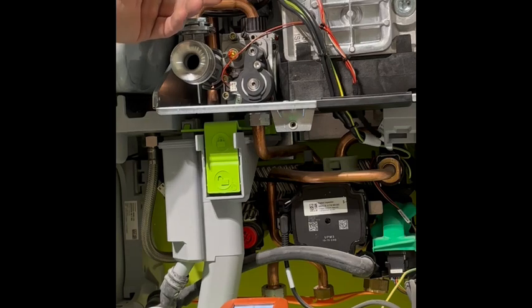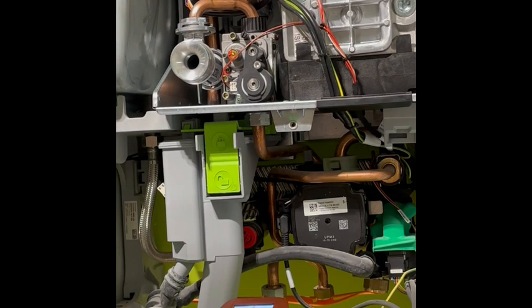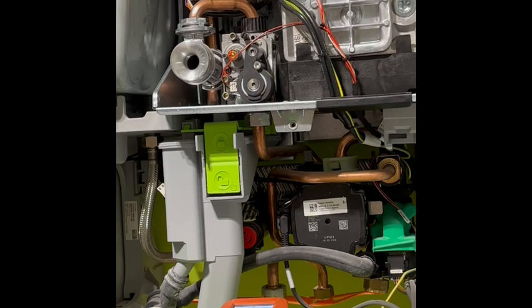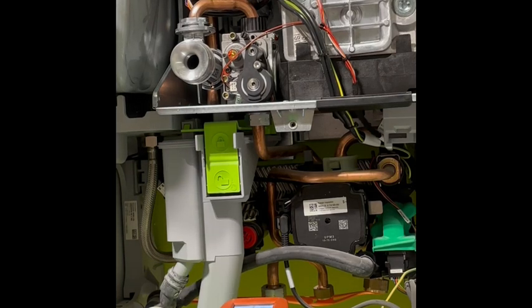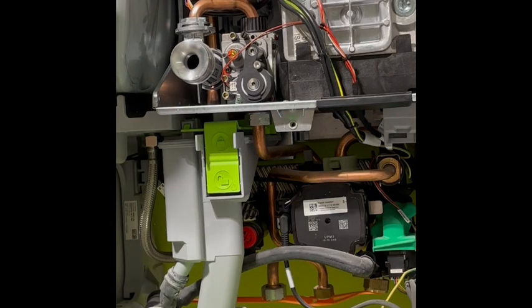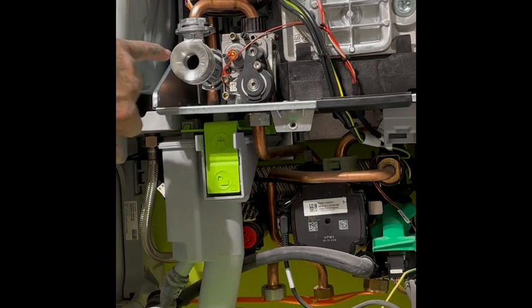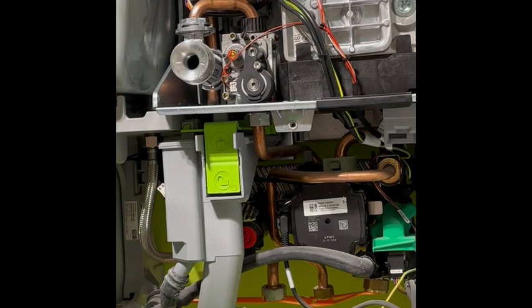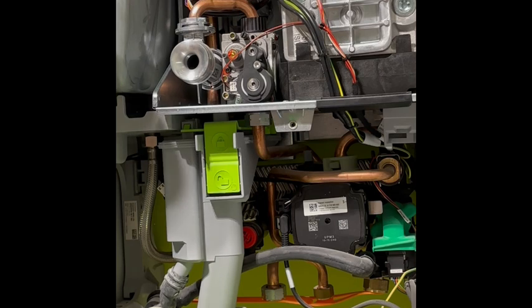That's going to be proved on this boiler by its pulse width modulation sensor, which is going to be back down to the circuit board. So we know the fan's run and purged the heat exchanger of any products of combustion or anything that was left in there, ready for a source of ignition and then the burner to fire. What's going to happen on this boiler is it's a pre-mixed burner, so it draws air in through there as well as gas, which is blown up into the burner. Okay? So if you remember, the three things that we need are gas, air and a source of ignition.